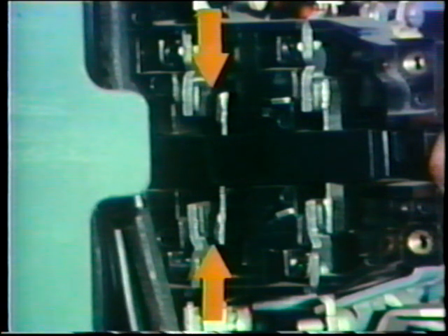Current is then unable to flow through the contacts and an incomplete circuit results. When contacts become contaminated, an increase in resistance may result. This high resistance causes excessive generation of heat, which can not only damage contacts, but also burn the insulation around the wires in a controller.